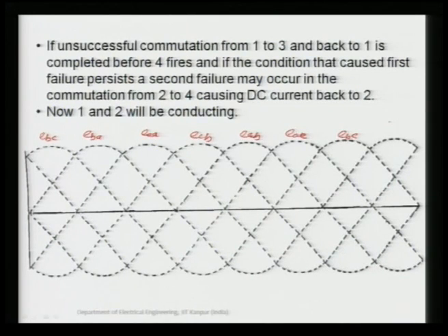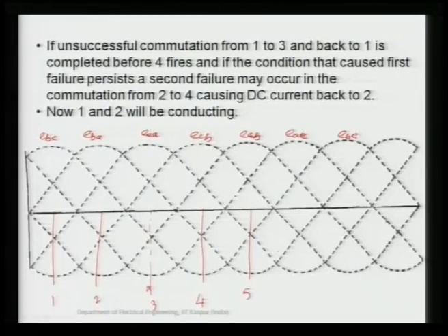Now here I am going to start directly from 3, because in this case 3 is to be fired, here your 2, here it is your 1. I just have to draw the sequence here. Again I have taken beta as 30 degrees, meaning alpha is 150 degrees. So it is 5, here it is 6, here it is 1, and here it is your 2 again. Okay.